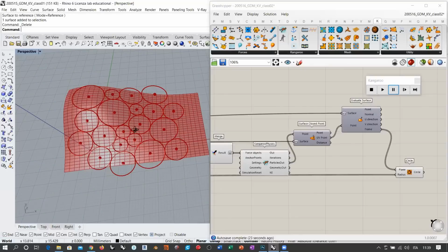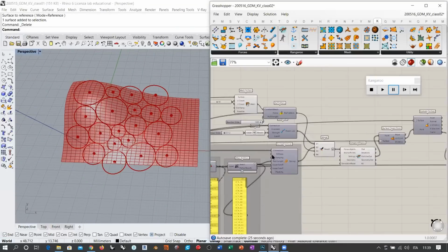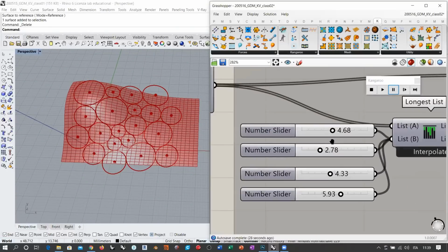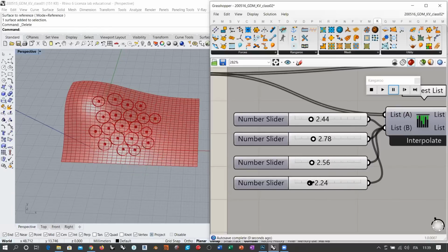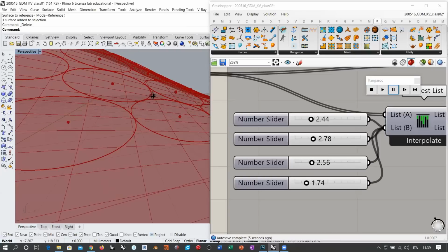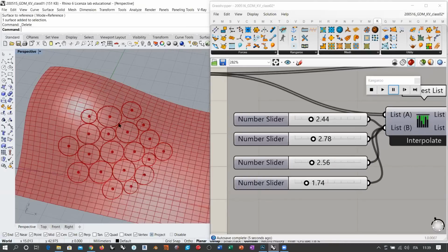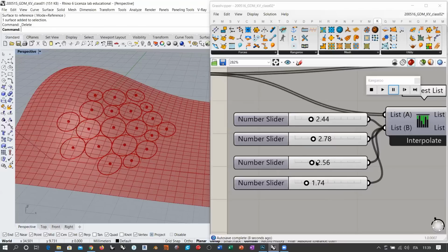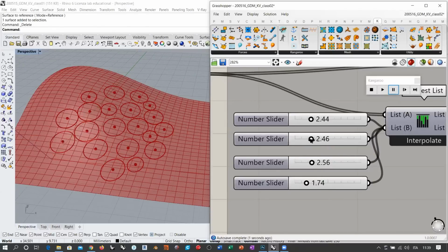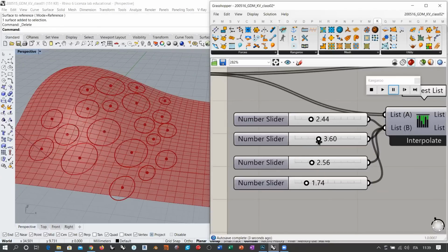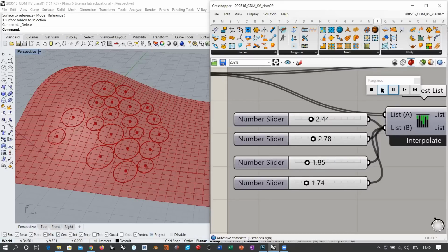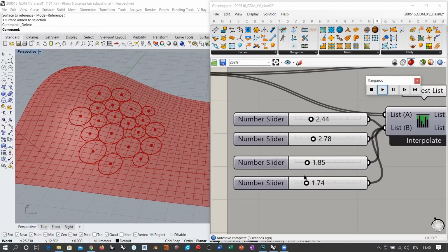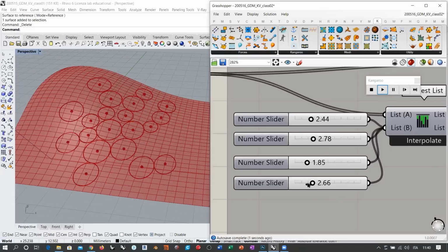But if you work with more proper values for your circles, like, I don't know, decreasing these, which are the biggest ones, then you can say that more or less you have the proper tangency between your circles. You see that now, for example, Kangaroo is moving like this, and this is because the simulation is in pause. I can play the simulation and have this happening in real time again.